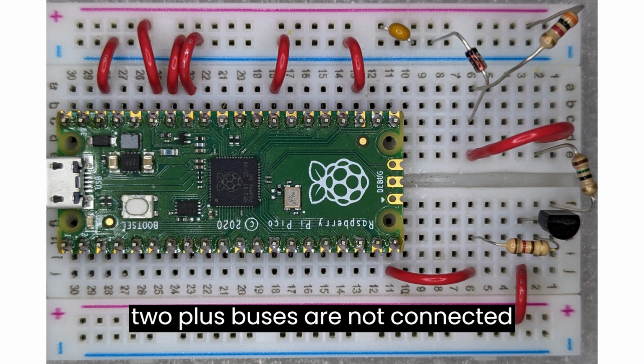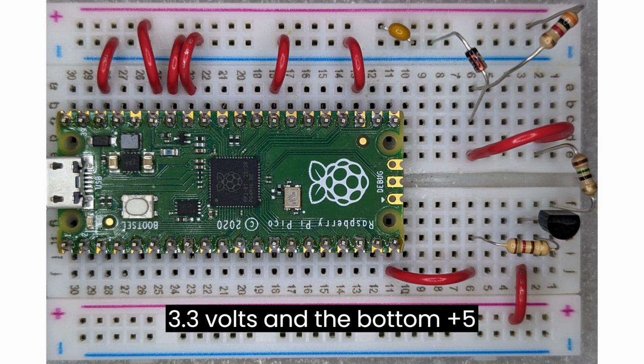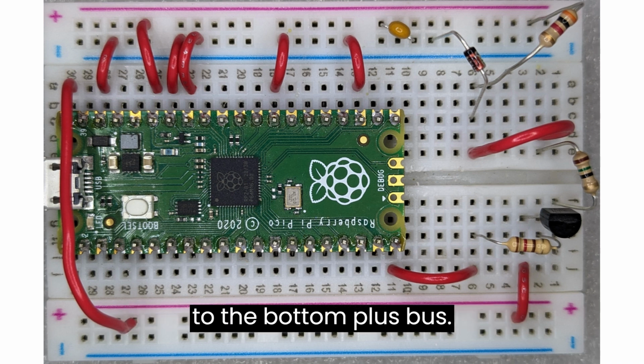Note that the two plus buses are not connected together. The top bus is 3.3 volts and the bottom one 5 volts. Add a jumper wire from Pico pin 40 to the bottom plus bus.